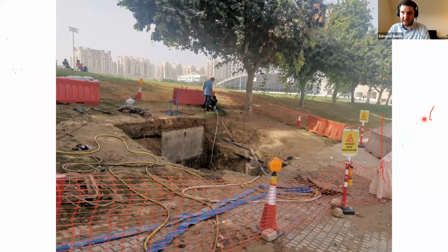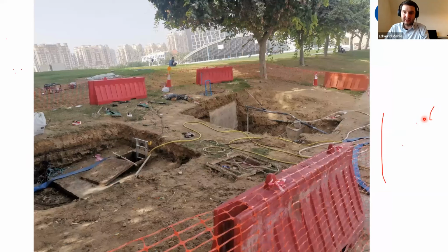But if you have some experience with the PipeMic and you know what to listen to, in the end, I told you, now we are on the leak. This was really the maximum intensity. You have the highest frequencies and you have the maximum intensity of the leak. And that was the case on this position where we had the joint, and in the end, we had this really precise excavation. Some more pictures of the excavation, just to have some more impressions of the project and what they are doing.